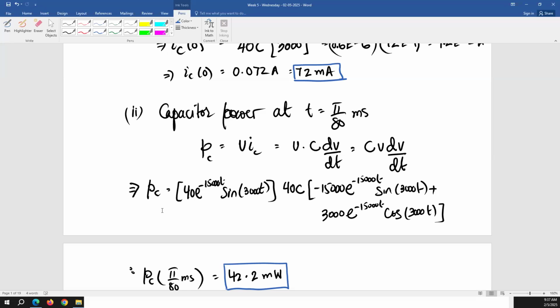But yeah, at that amount of time, basically, in engineering, we call it an impulse. Impulse means that a signal has a very narrow width, but its height is infinity. That's a signal which is called an impulse signal. Basically, its height is infinity, but its width is almost zero, and we assume that the total area of that signal is 1.